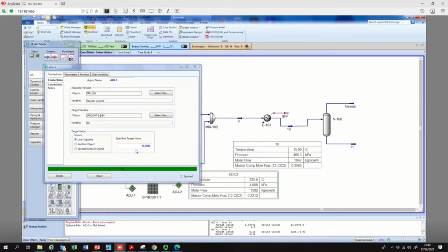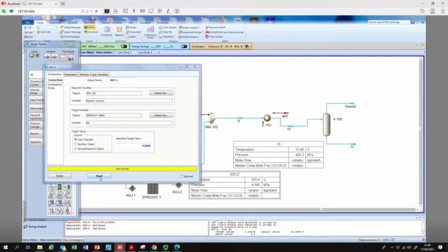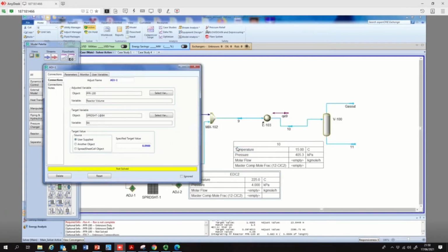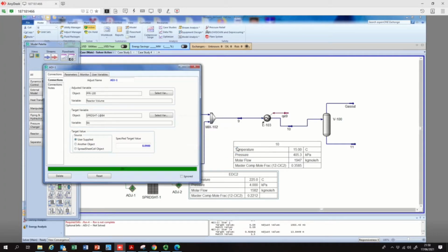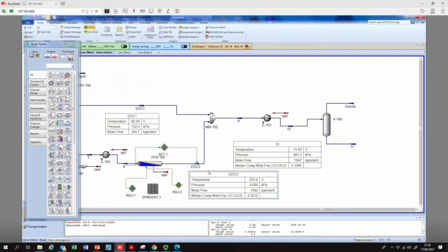So no big difference. So let's put it back to the original value, 0.09. I thought increasing the pyrolysis time may increase the conversion, and then the mole fraction of ethylene dichloride in the product stream would improve. Nothing is happening, so let's keep it at the original value.